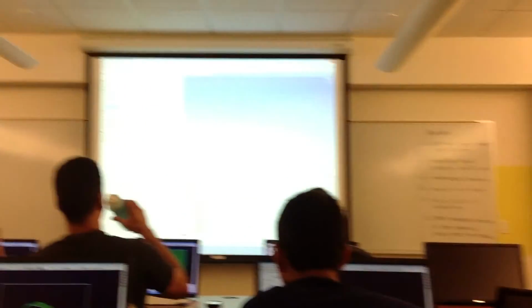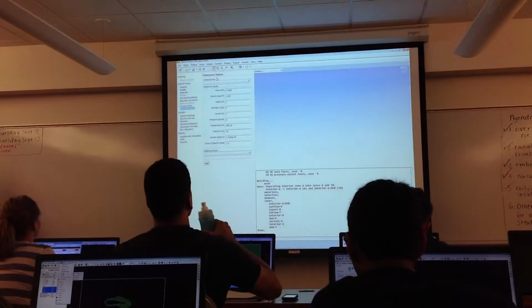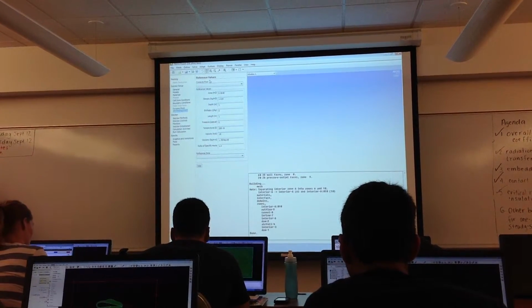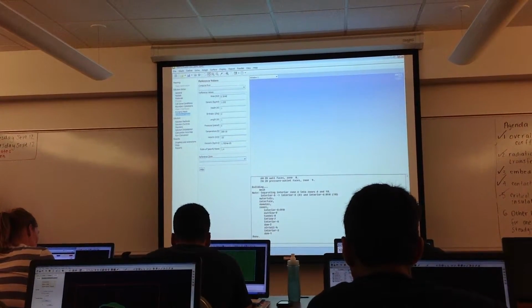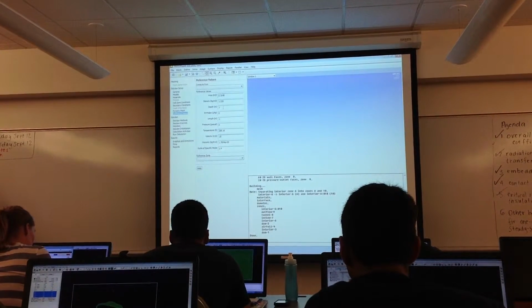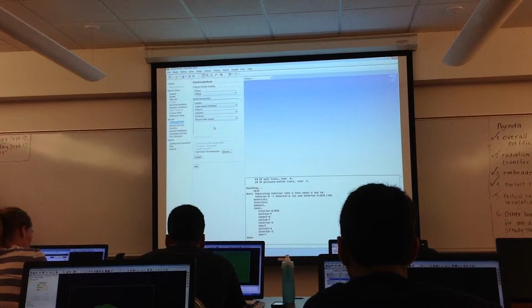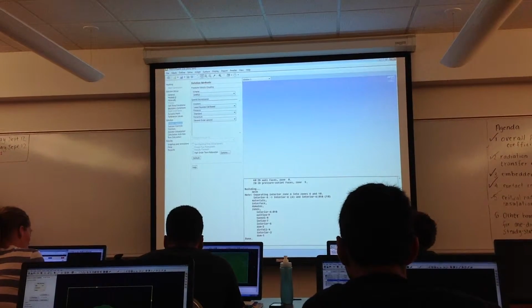Okay, so the reference conditions are set. These are important because when you see the lift and drag coefficient, they'll be appropriate values based on these reference conditions. This is the planform area, and these are the conditions it's operating at. Solution method. So we're done with the solution setup.